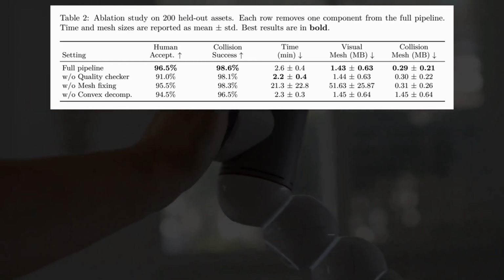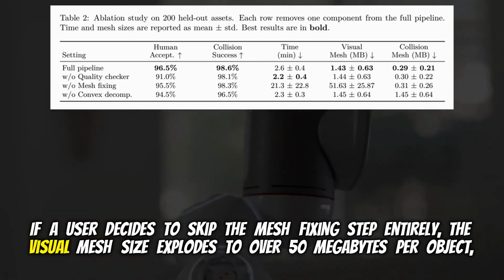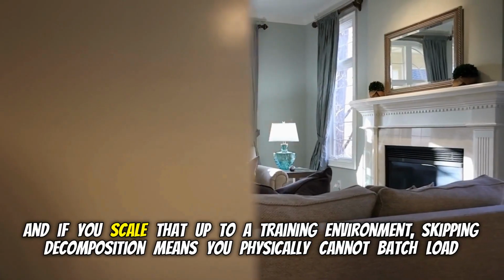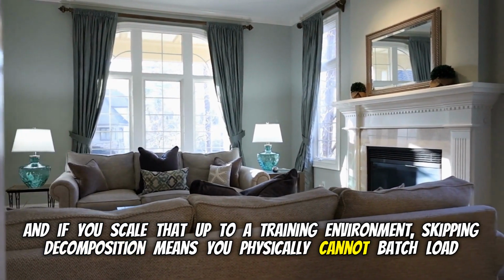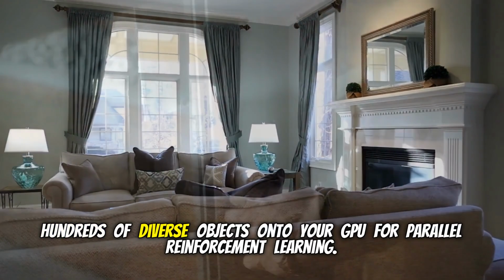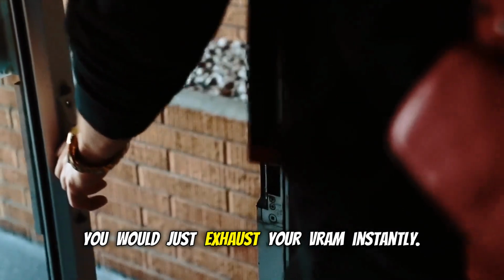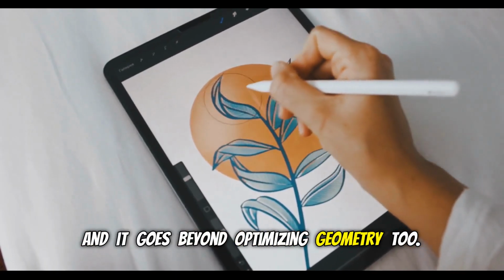And it gets worse. If a user decides to skip the mesh fixing step entirely, the visual mesh size explodes to over 50 megabytes per object, multiplying processing time by 8. And if you scale that up to a training environment, skipping decomposition means you physically cannot batch load hundreds of diverse objects onto your GPU for parallel reinforcement learning. You would just exhaust your VRAM instantly. Instantly. And it goes beyond optimizing geometry, too.